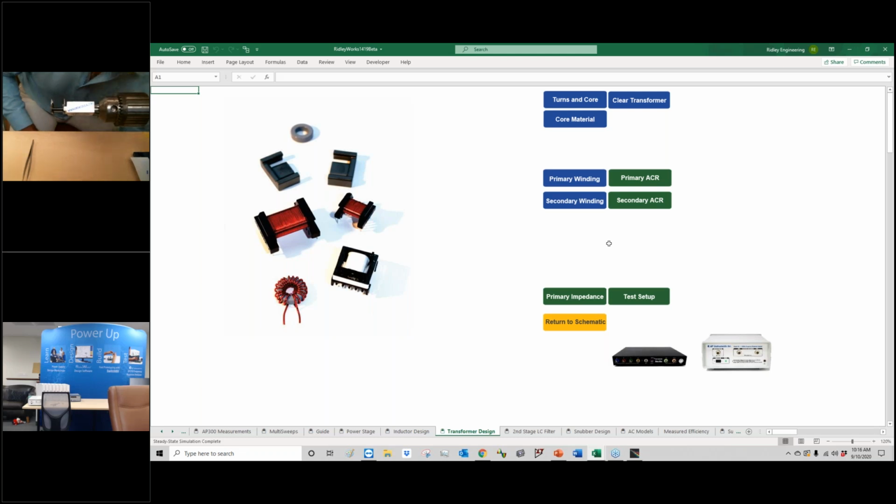Okay, I do a thing here where I take my wire right here and I put it down on the floor. I put it down on the floor because it'll come off the spool nicely as I wind it. You don't want to get any kinks in the wire. So I'm going to start here on pin 1 and wrap the wire around. And we set the turns count to 0, and then we push the button, and off we go.